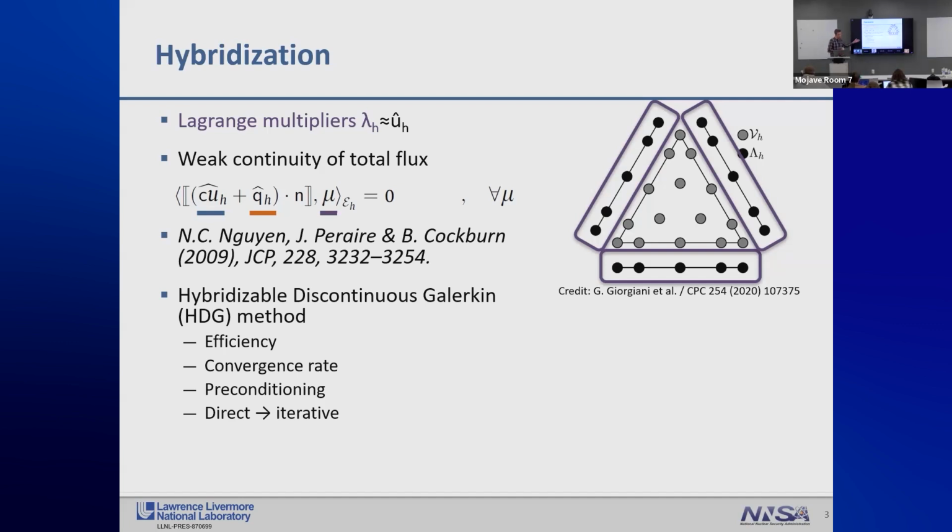And also preconditioning is way easier because the resulting system is structurally similar to low-order matrices. And thanks to all this, we can move away from direct solvers, which we typically need for stiff problems, and use just classical iterative solvers, which scale much better to HPC clusters and typically have overall lower computational costs.